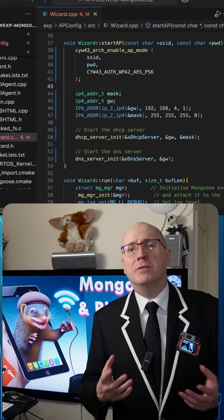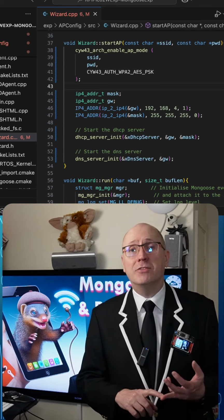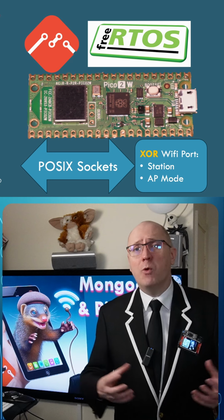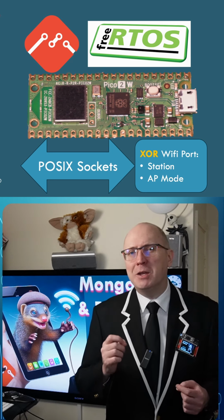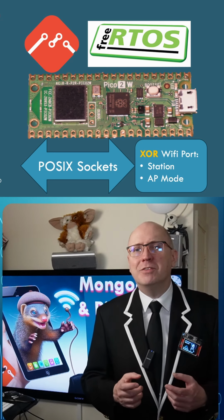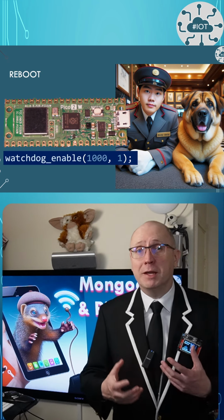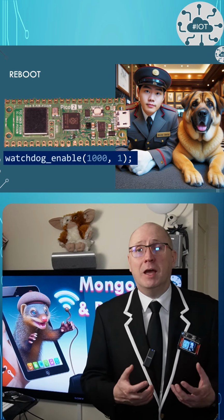It's just a few lines of code to start up the AP mode and the DHCP and DNS service. You don't need to do anything to Mongoose to make it connect to the AP mode network, provided you use AP mode on its own and not the station mode at the same time. Using them together is a bit more involved. To switch between them, I'm actually going to reboot the Pico completely. I'll do that using the Watchdog timer from the SDK.